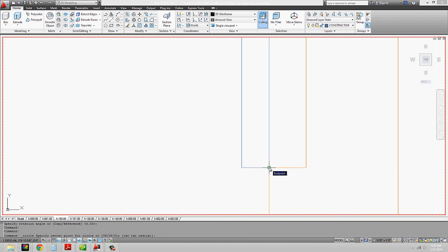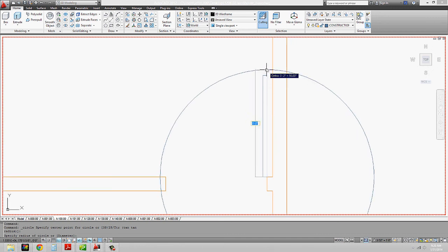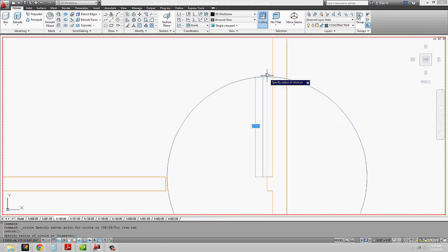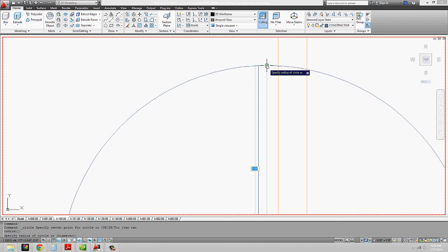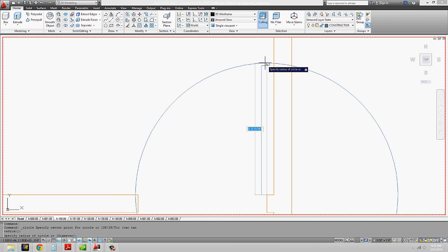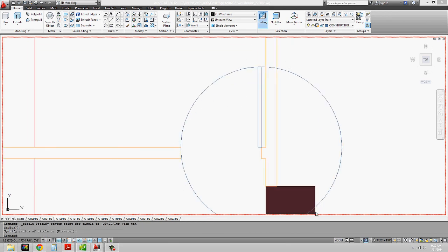So you want to hit where the wall meets the hinge. I'm going to click there. I'm going to bring my circle up, so the radius up, and I'm going to click on this edge, okay, still on the hinge side of the edge of my door, and it's going to set the diameter of my circle, okay, based upon that radius that I just set.